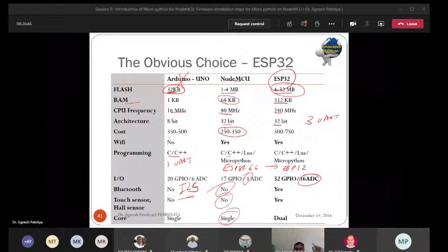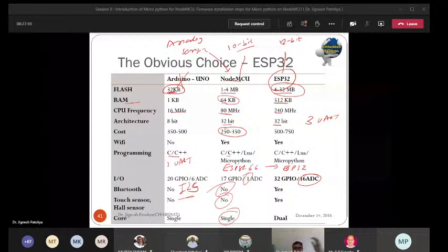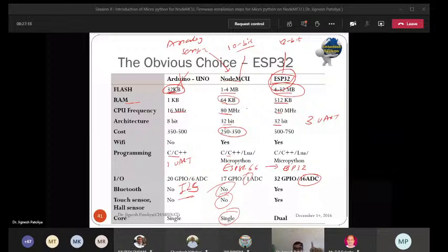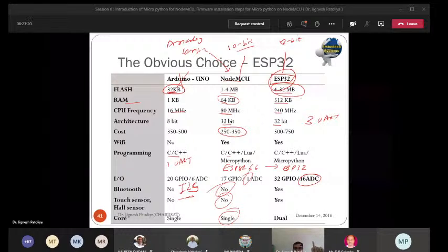And again, one very interesting thing in this NodeMCU and ESP32: here ADC size is only 10-bit, and here the size of ADC is 12-bit. Then be careful if your student interfaces any analog sensor with NodeMCU, and he or she emails this code and you test your code using ESP32, then the answers in this case will definitely differ. Why differ? Because here is the difference in size, 10-bit and 12-bit.